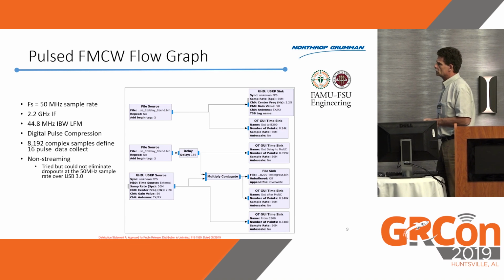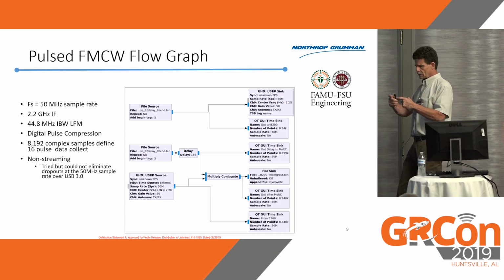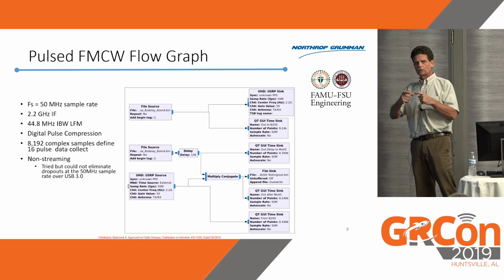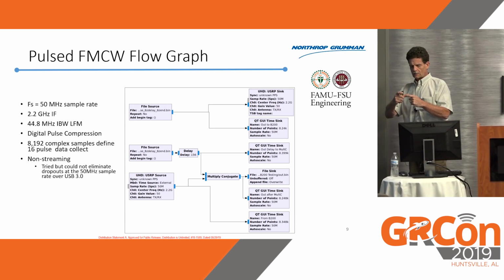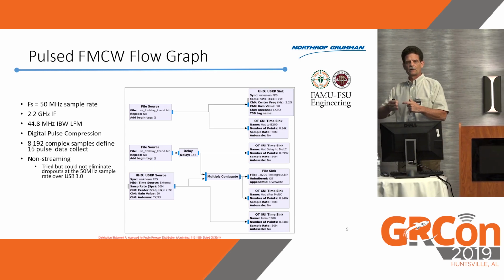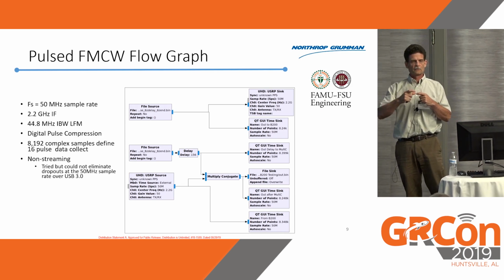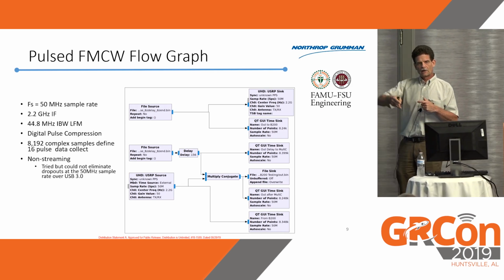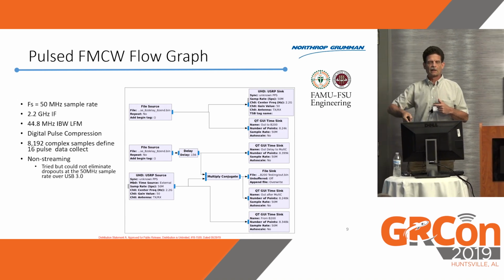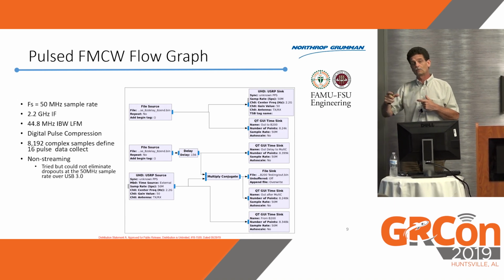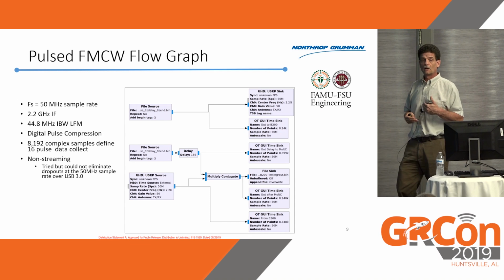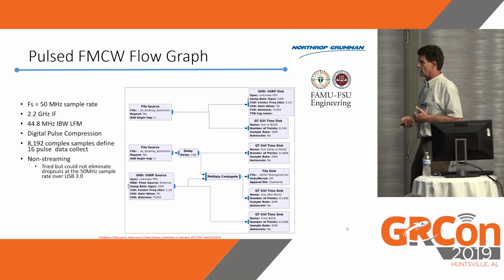And then we do the conjugate multiply with a version of the transmit. So this is the match filter. If you take two LFMs, two chirps, and you multiply them together, and they come back at different times, you get an IF frequency. It basically compresses into a single frequency. So if something comes back at a further range and multiplies, you'll get a higher frequency down at IF, at baseband. So you can separate range in the frequency domain by how it multiplies out.